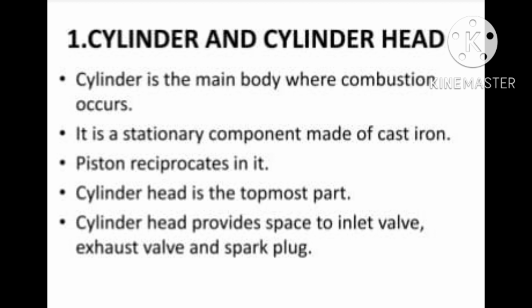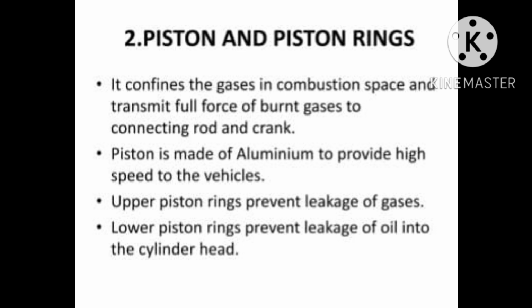Okay. Now second part is piston and piston rings. Very important part of engine. Piston, it confines the gases in combustion space and transmit the full force of burnt gases to the connecting rod and crank. Now piston is generally made up of aluminium to provide the high speed of the vehicles.